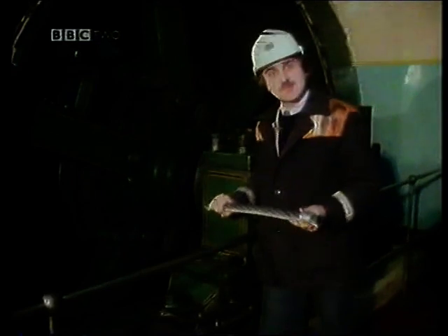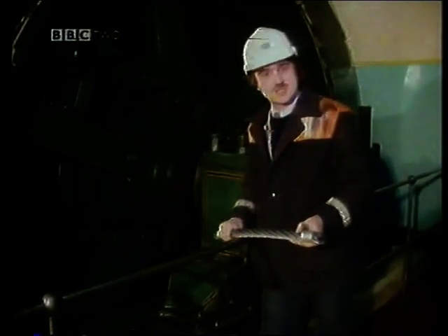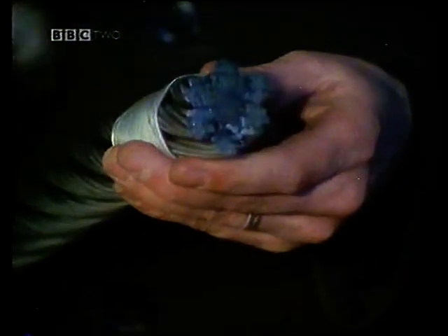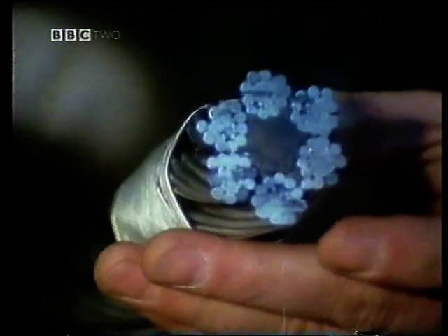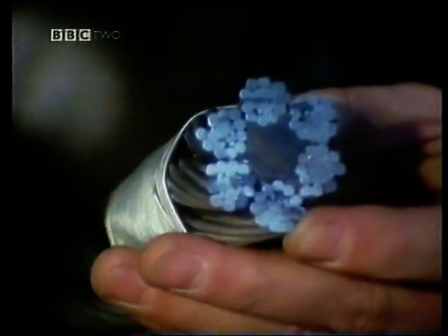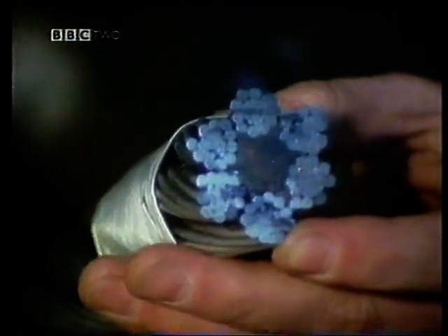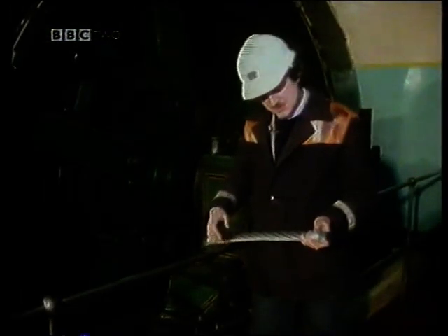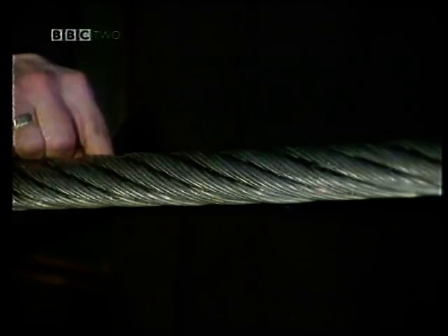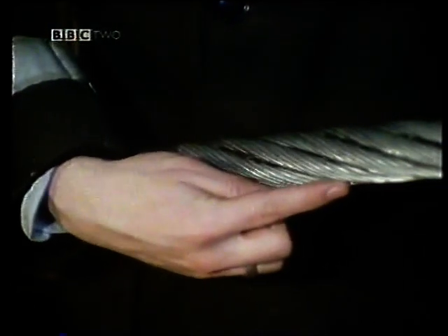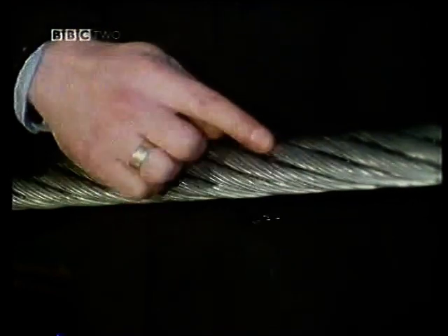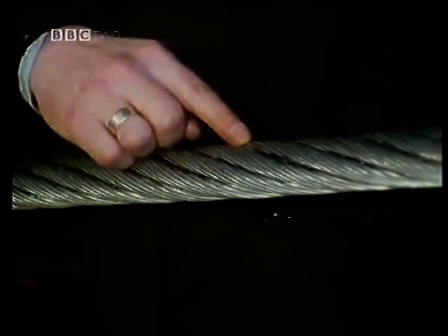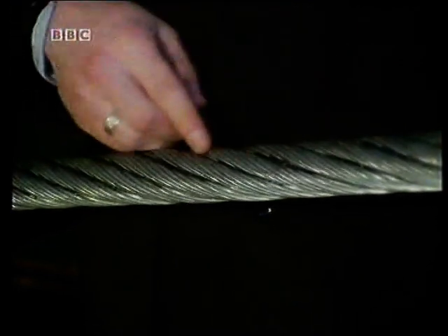Well, the rope itself has a number of features which increase its capabilities. If we look at a section, we'll see that it's made up of a number of thin steel strands, which means that it's more flexible in bending than an equivalent solid steel rope. Also, the strands themselves are twisted around the rope, so that as the rope winds onto the drum, any part of a strand will be first on the bottom, close to the drum where it will be in compression, and then on the top, away from the drum, where it will be in tension, thus evening out the stresses on any single strand.